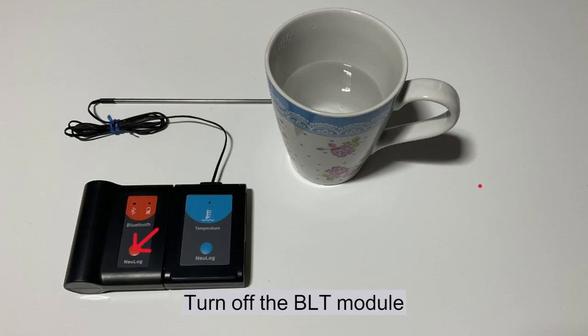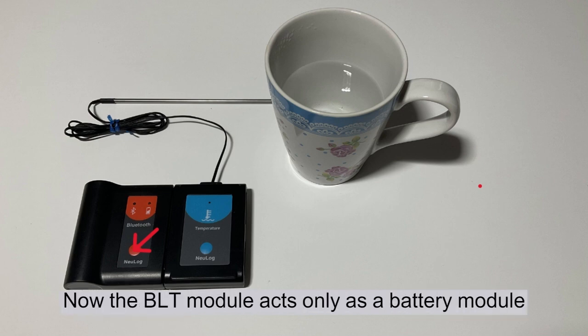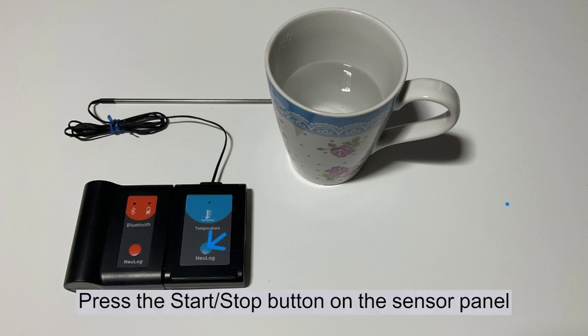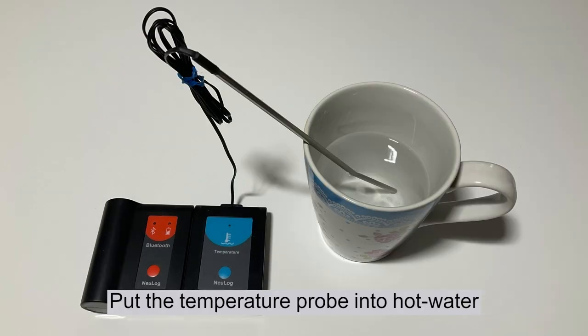Turn off the BLT module by pressing its orange button for 5 seconds. Now the BLT module acts only as a battery module. Press the Start/Stop button on the sensor panel. The LED on the sensor blinks to indicate waiting for trigger. Put the temperature probe into hot water.